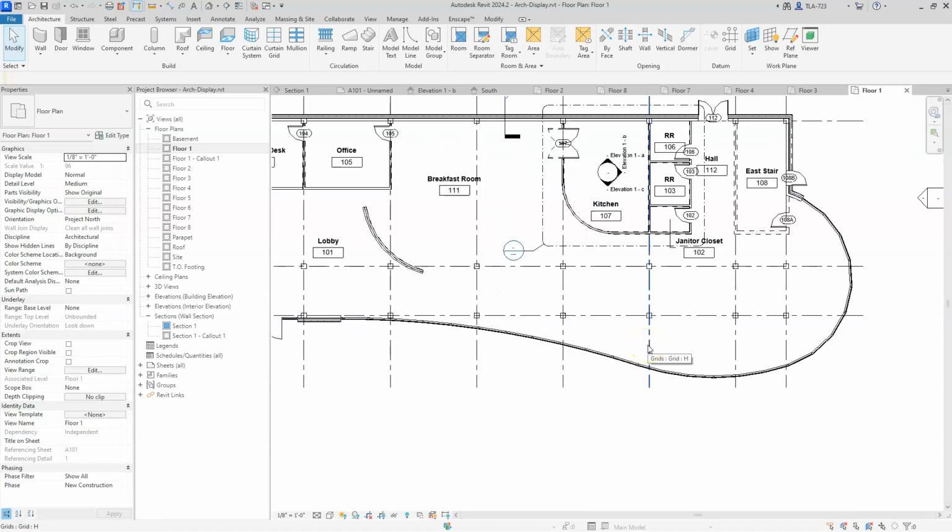It's a little bit confusing, a lot in that segment, but just remember: temporary hide is for when you just need to hide something for the purpose of cleaning up the drawing for drafting, and hide and reveal by right clicking are the more semi-permanent hiding things that we want to do. So we'll talk about that more in the future to remind you, but for now, just understand there are 2 different ways to hide stuff.